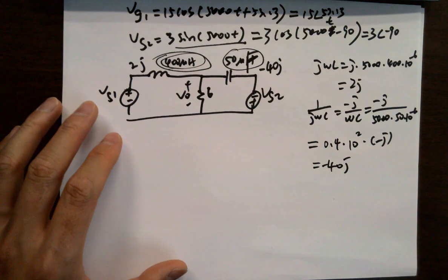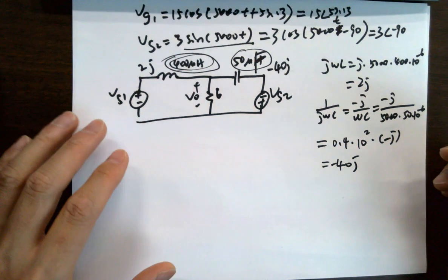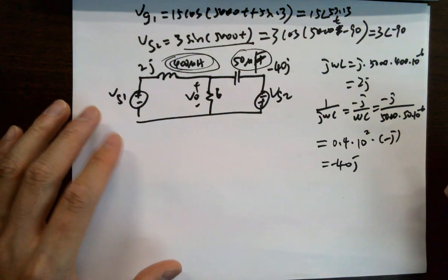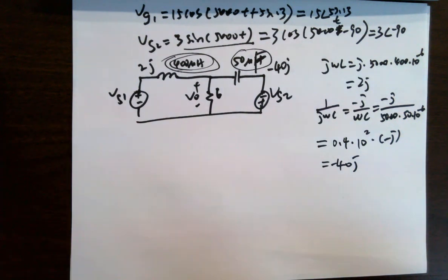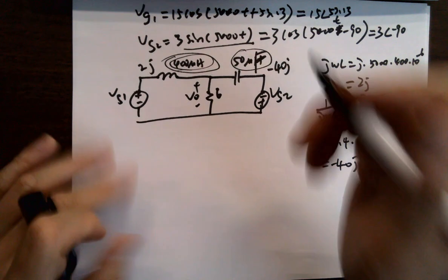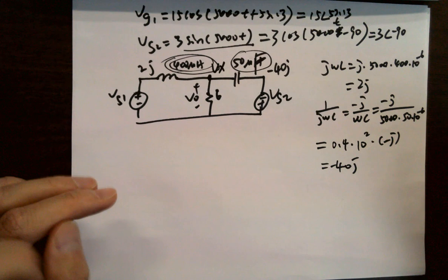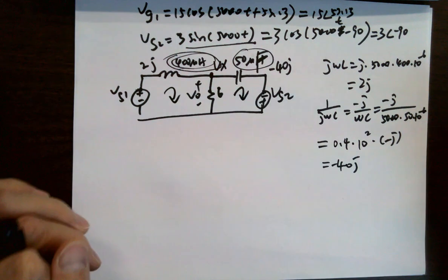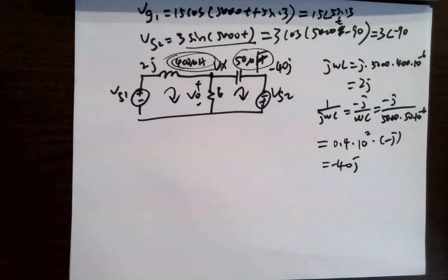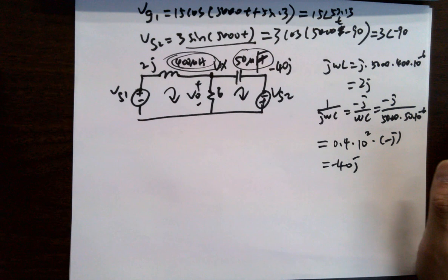Do you have a question or no? No? So you can use 2 different methods to solve a problem like this. I have learned 2 mainly, but you can also do superposition, but I don't recommend it. The first one is called the node voltage method, and the second one is called the mesh current method, right? You can use either one. The pain is pretty much equivalent. It's a lot of calculations. No difference. Just pick one, okay?